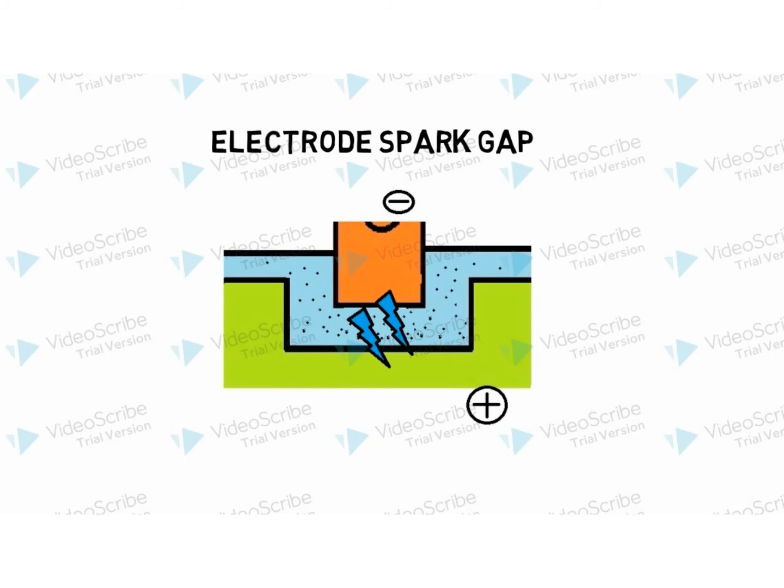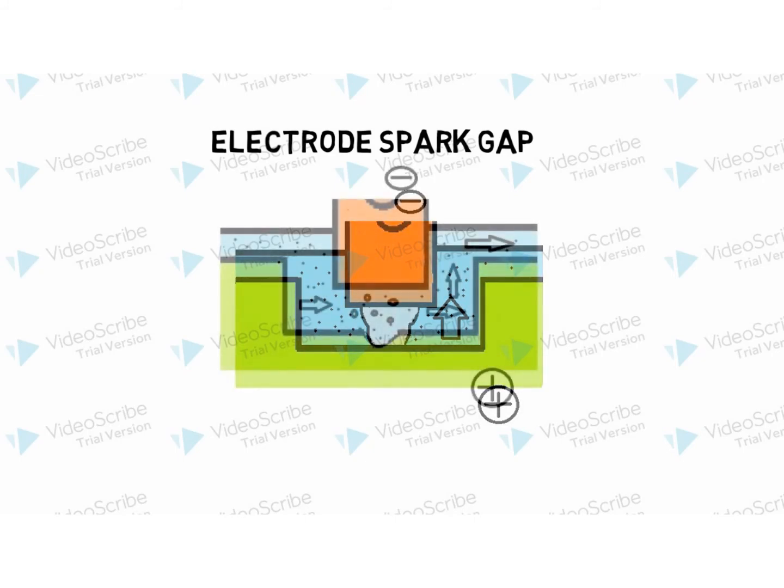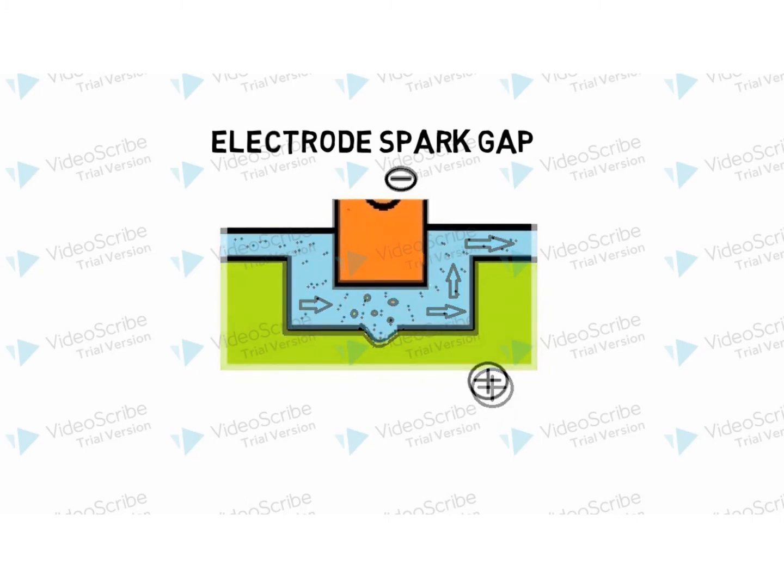This creates high pressure and heat at the spark contact point, and the metal from the workpiece and even the electrode is vaporized to form a vapor bubble, which expands to cut off the spark. This bubble is then cooled as the spark ends from the generator and the dielectric fluid rushes in and flushes out the solidified metal particles from the workpiece and the gap. The whole process leaves the machined workpiece at the spark contact.